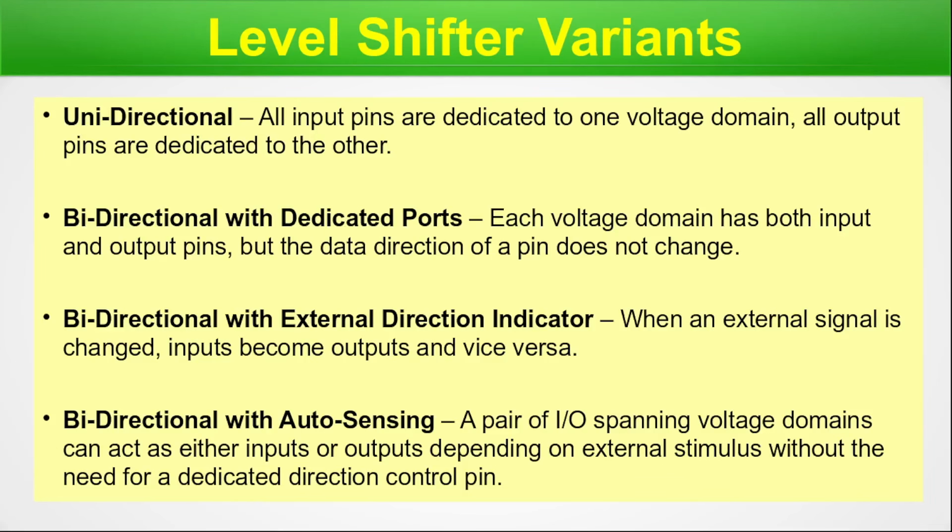Where will you find all this information? When you receive the documentation of a design kit, that is DK or PDK, from the vendor, you will get text documentation with the graphical representation and data sheet. There you will find all the details of what types of level shifters are there, how you can use them, and what the categories are. These two slides will help you when you are actually designing in VLSI.